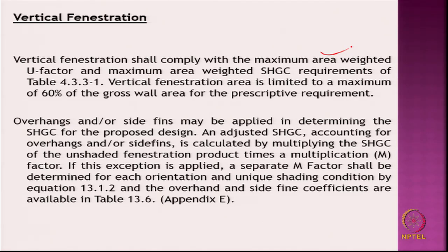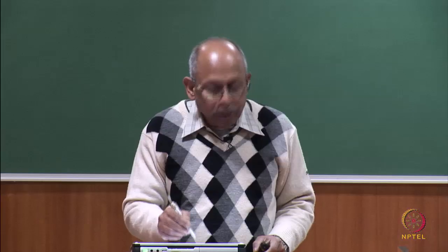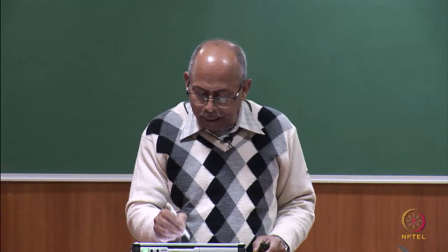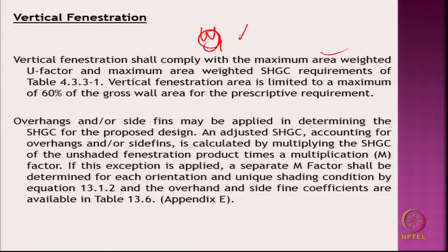Now, glass will have a frame, a window will have a frame also, right. So, some glazed area, the frame portion also. So, take the weighted average, for example, area of the frame, A_F, times U frame, plus area of the glass, A_G, times U of the glass, right.